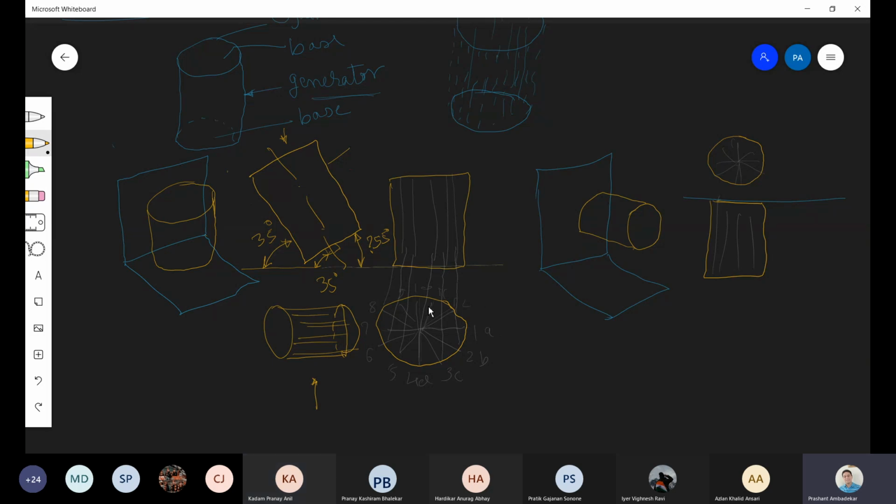If you don't divide the circle into 12 parts, you will not be able to get these points. Which points? See, this is a circle, correct? This circle is seen here in the top view, correct? Yes. But as you are inclining it like this, will it still be a circle from the top view? No, sir. It will become an ellipse. Okay. And at the moment when this angle becomes 0, this will become a straight line, correct?